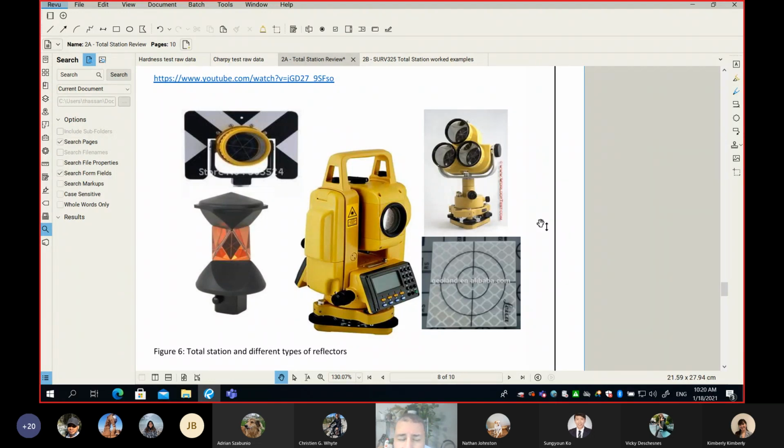Why is that? Because I can tell you, if you have some experience in surveying, maintaining the rod vertically is a headache. Oh my God, look at this. What if it's a little bit windy? And what if your surveyor is tired? Unintentionally, the rod will be out of plumb and you have some errors. However, when you install this assembly on the right on a tripod, you make sure 100% that the prism is above the point of interest.